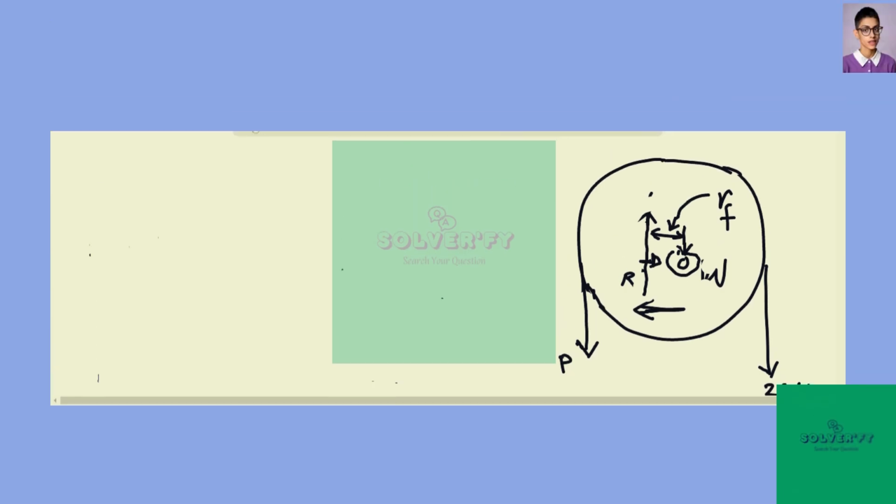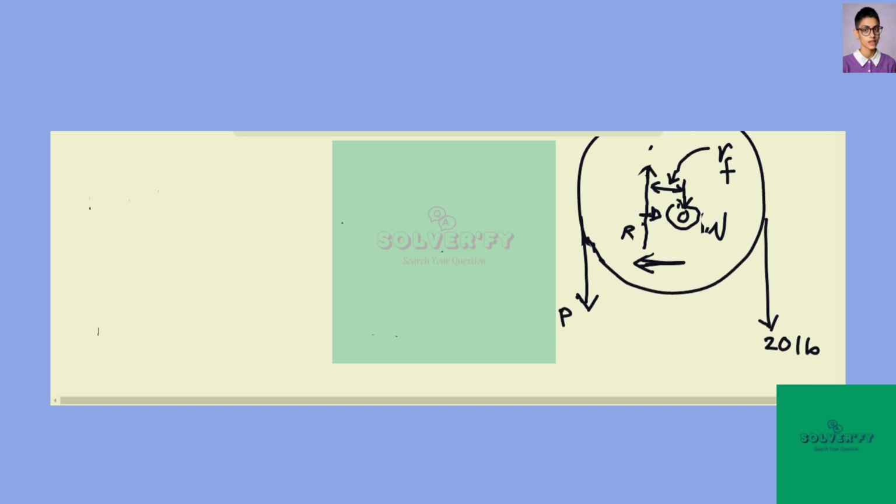Problem on the friction and lifting force. Now look at the diagram shown on the board. We want to determine the force P that will be able to lift the 20 lb load. To solve this problem, we must understand that it involves a journal bearing, a pulley mounted on an axle. So the first thing to do is to determine what we call the friction circle radius and apply equilibrium to the system, and solve the problem.